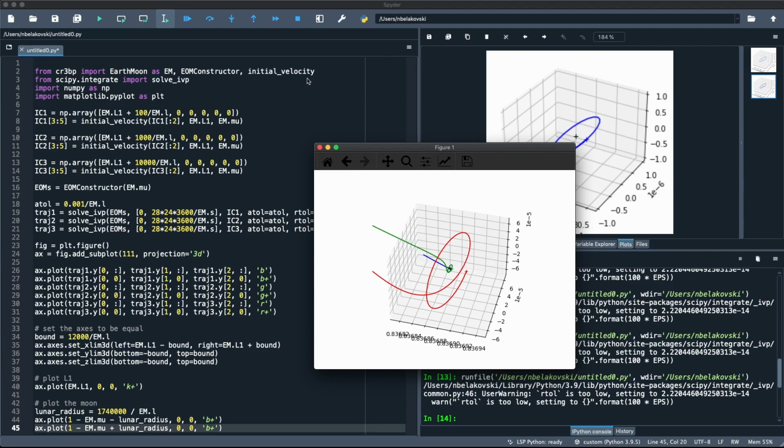Now, we're going to allow that delta v to grow, so we're not just going to execute it anytime there's a difference, because we're going to assume that our thrusters don't have arbitrary precision. If the delta v is saying that I need to add 2 nanometers per second to my velocity, that's probably not very realistic.